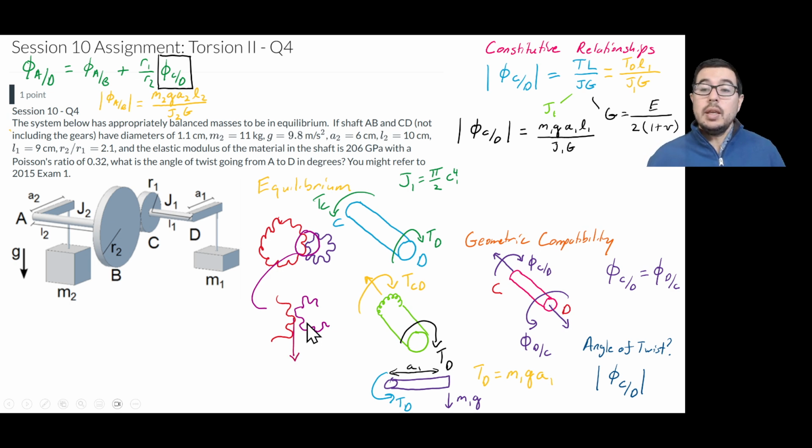We could say, if this red gear is rotating counterclockwise, that it has upon it a force from the purple gear pushing it down. And we can say that the red gear, if it's rotating counterclockwise again, is pushing up on a tooth on the purple gear.